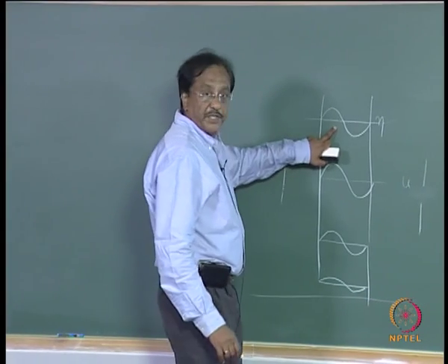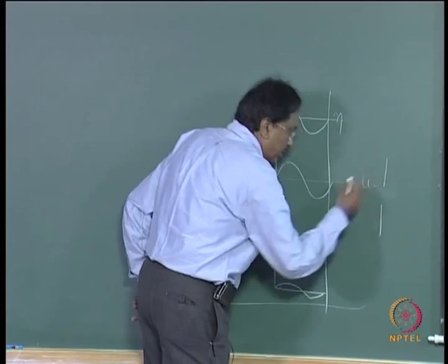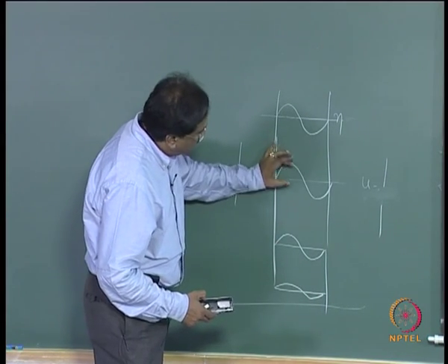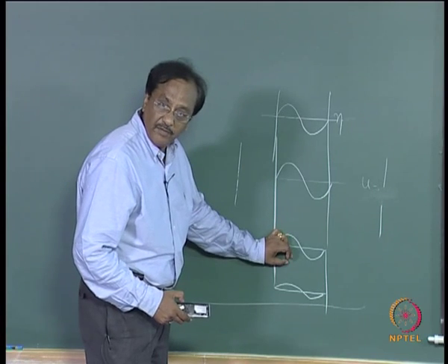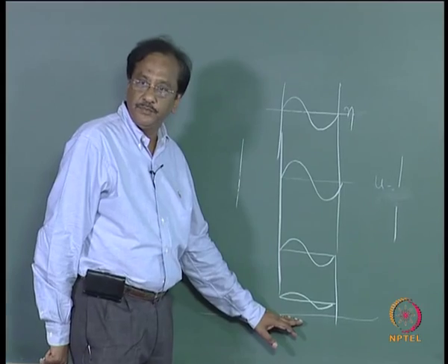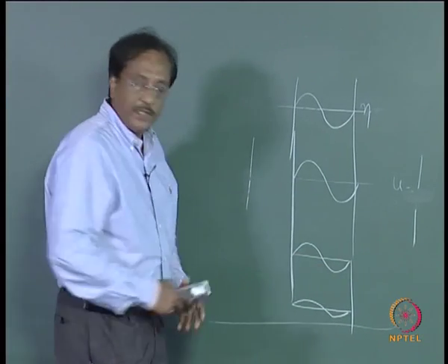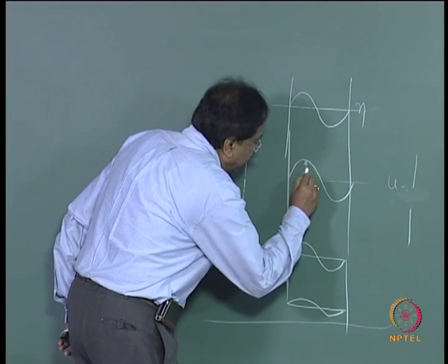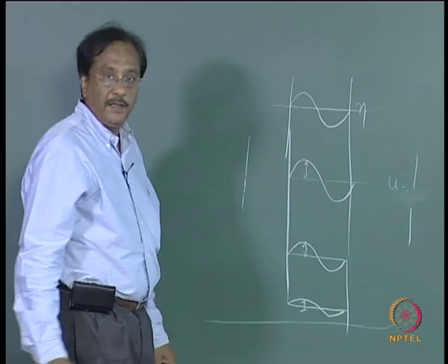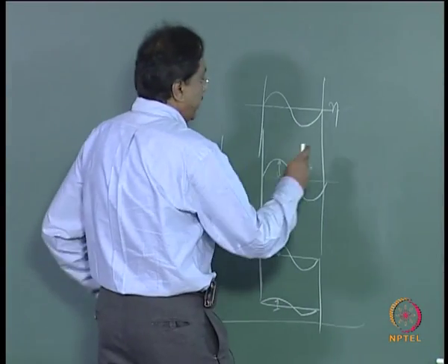So this is the variation of eta. So this will be u at somewhere close to the free surface, and then you see that the magnitude of the horizontal particle velocity will be reducing as you go towards the seabed, and at each elevation it will be a sine curve. Now I am talking only about the magnitude. If I plot that, how does the variation look like?